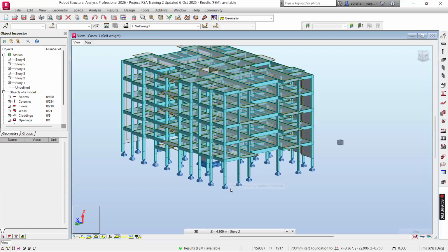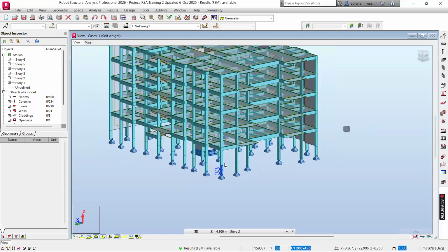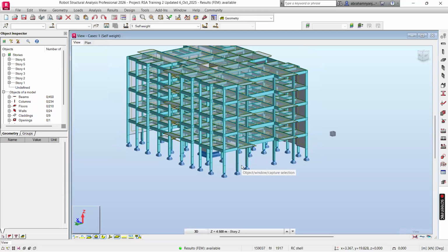Friction piles utilize the friction resistance on the sides to counterbalance whatever forces are applied. So what we are going to deal with are the shallow foundations, the pad, the raft, the strip, meaning they're going to dissipate loads at a shallow depth. So we have a very good firm strata probably at a small depth.